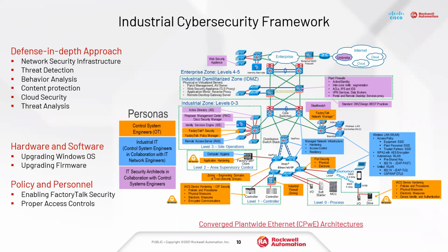We also have user manuals and design guidelines to help improve the security of your industrial automation system. This isn't just looking at implementation of something like FactoryTalk security at the controller level, but it's also looking at how we would harden the entire control system. So setting up the domain controller, setting up your firewall rules, looking at the overall posture when it comes to all of the computers, all of the tie-ins, some of the procedures, the policies that we would recommend.